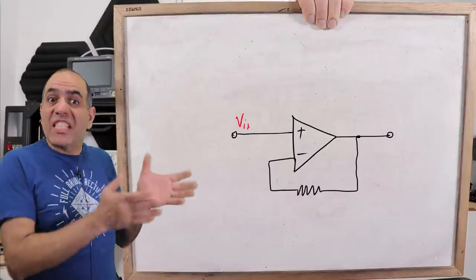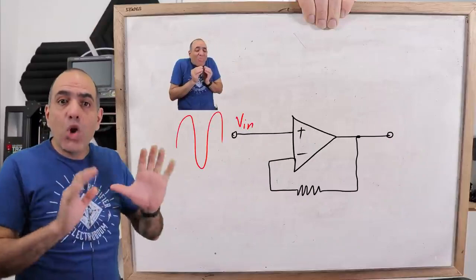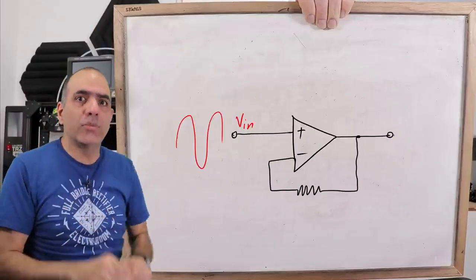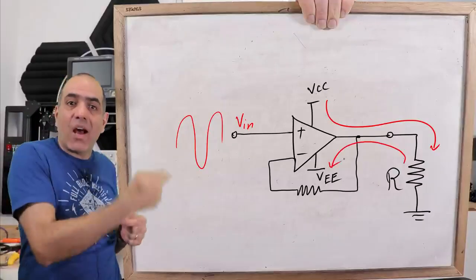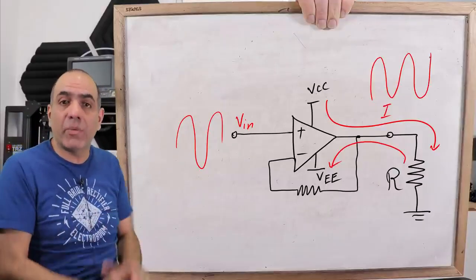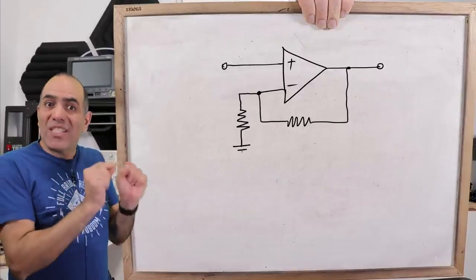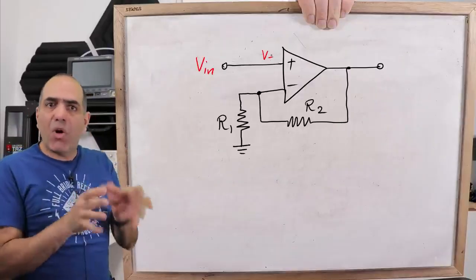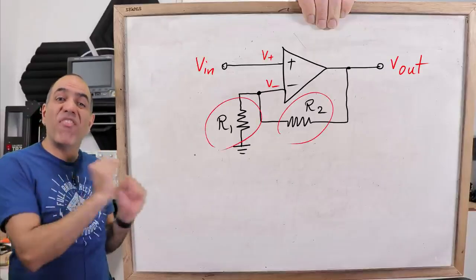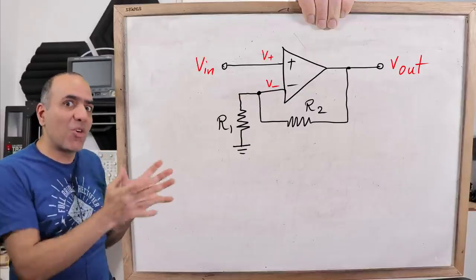You can connect a sensitive signal to the input without loading it, that otherwise would be disturbed by even a minimal load. The buffer copies the signal at the output and connects it to another circuit that may safely draw current from it. But you can also add more resistors to your feedback path. Now you are dividing the output voltage over 2 resistors and feeding it to V-. Let's calculate what's going on here.